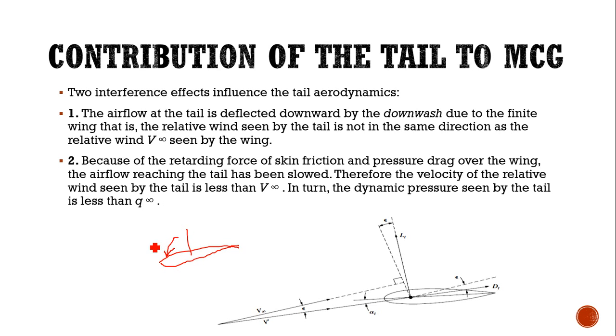So a pitch down moment acts on the airplane, and if it is a statically stable aircraft, an opposite moment, a clockwise moment, should occur on the airplane to produce the restoring force and bring the aircraft back to the equilibrium position. Suppose an anti-clockwise moment acts on the airplane, it means the aircraft cannot be brought back to the equilibrium position.